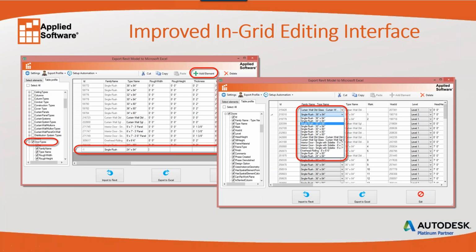a different type. In the current version of BIM Connect, you have to type in the family and the type name, which if you get a typo, that's not going to work, right? It'll fail on the import. This one gives you a drop-down list so you can choose from all the existing families and types. And these drop-down lists will appear anywhere where it makes sense for them to be.